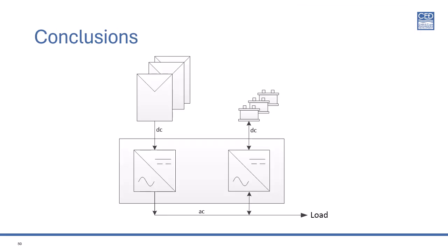Summarising all of this, we can see that in order to supply the peak load, we need to have at least 40 kilowatts peak capacity from the solar panels, at least 179 kilowatt hours of battery capacity, and solar inverters totaling well in excess of 23 kilowatts. In fact, the inverters must be capable of accepting the full load from the panels without damage anyway.